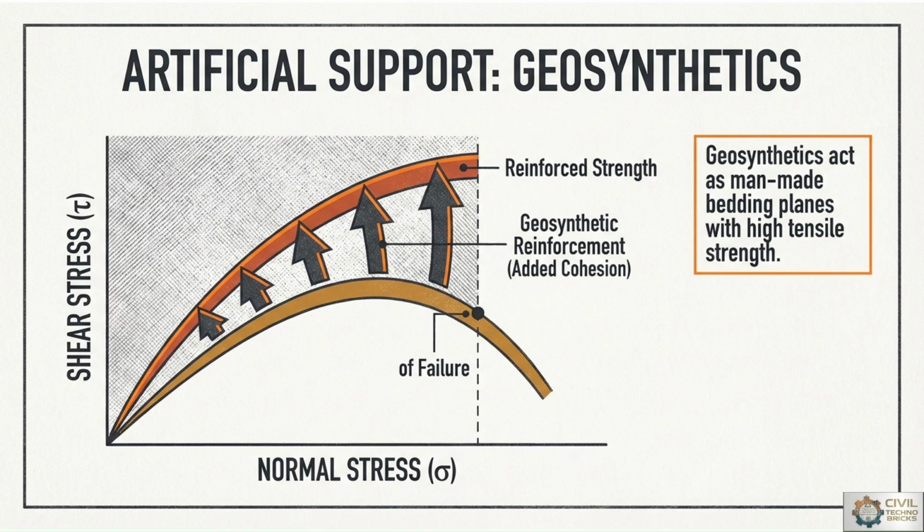So if we use geosynthetics, then we can improve that failure to the reinforced strength by using geosynthetic reinforcement, which is an add-on to minimize the failure, or to improve the efficiency of the existing soil layer or rock layer which is not as hard. Geosynthetics are additional material inserted as powder, net or sheets into the soil layers.